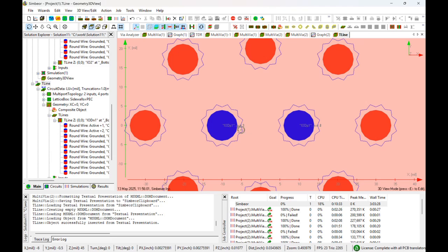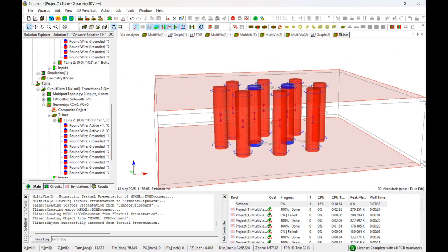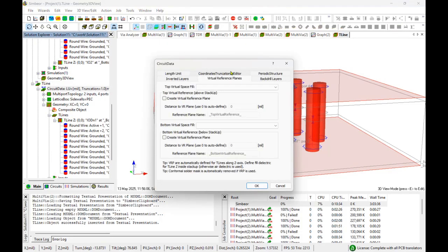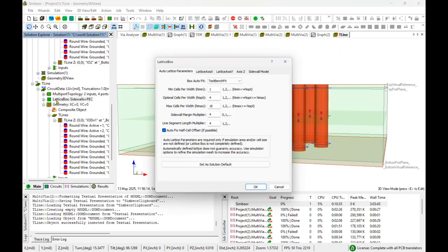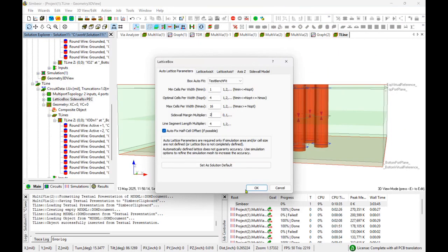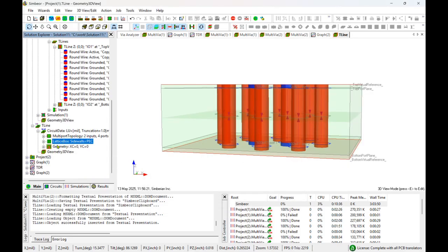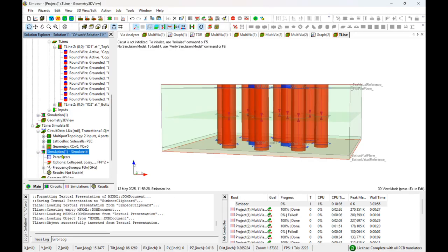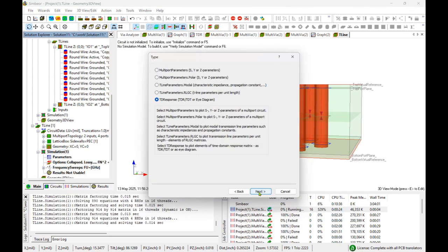So I switch off the editor and use D. This is a transmission line. And the only thing I need to do is, again, we need to improve it. Put FR4 filling. And now we fill with FR4. I can reduce the simulation area here just to run the simulation faster and run the analysis, and reuse the simulation from the other. Run the analysis, F7.